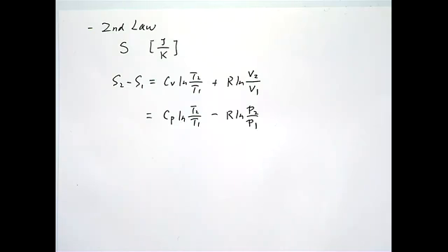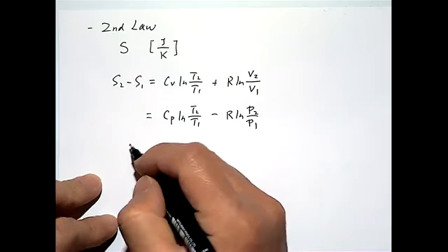The purpose of deriving the Gibbs equation is so we can calculate the change in entropy from one state to the other. When we derived the Gibbs equation, if you recall, we started from a closed system going through a reversible process. People later realized that this equation is actually more universal. You can apply it to irreversible processes as well as open systems. So the Gibbs equation is a universal way to calculate the entropy change.